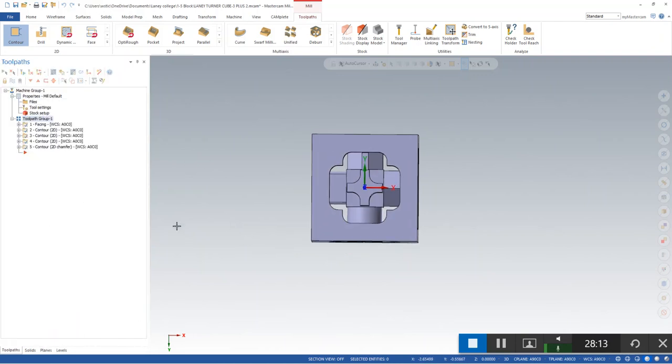Alright. What I can do is call this toolpath group right here. I'm going to click on that and call it op1 A0C0. And then I'll create a new toolpath group for the next operation.